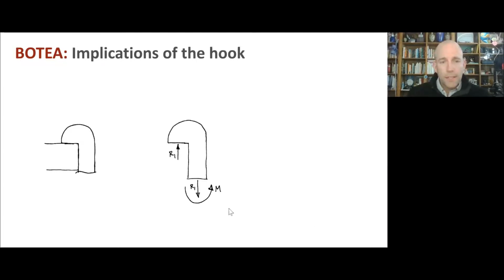And bending moments we try to avoid often in these mass efficient design cases because they tend to develop high stresses on the edges of the material and low stress in the middle. And that tends to result in not very mass efficient design because the middle part isn't really carrying its load.